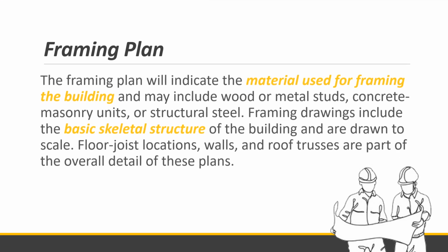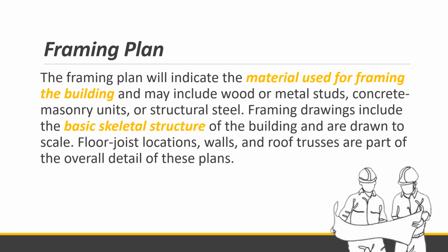Now, next is the framing plan. The framing plan will indicate the material used for framing of the building. This may include wood or metal studs, or concrete masonry units, or structural steels. Framing drawings include the basic skeletal structure of the building and are drawn to scale.